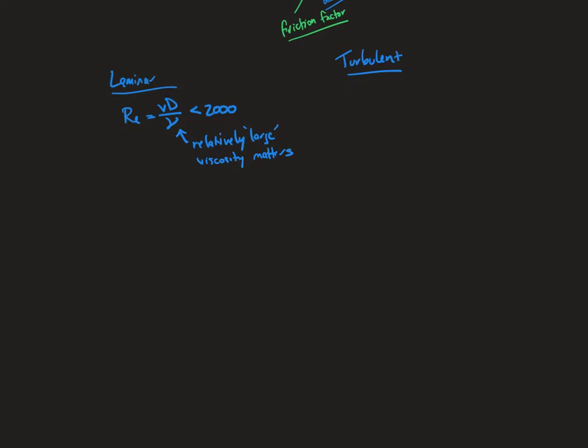The other thing to remember is that if we're talking about flow in a pipe, it's going to have a nice parabolic shape, which indicates that V bar is V max over 2, which is why alpha equals 2.0. We know all this. That's all review.